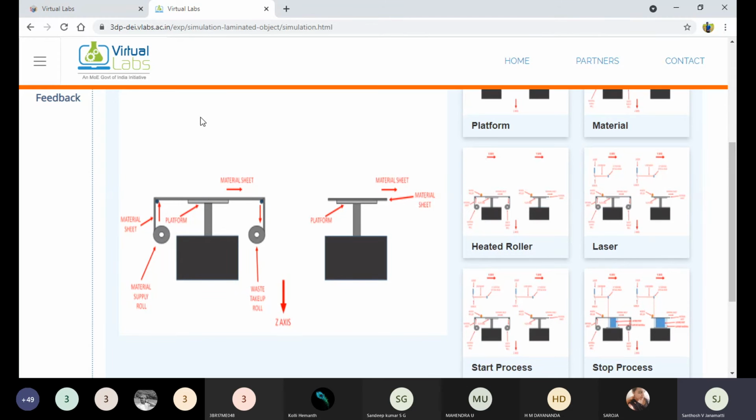At the top we can see the laser action, the scanning laser. Before that, the heating rollers, or heated rollers, are here. Because this is a solid sheet and it is at room temperature, we need to fuse this sheet. Once it turns into the plastic state, we need to fuse it, so we need to supply the required fusing temperature from the heating rollers.